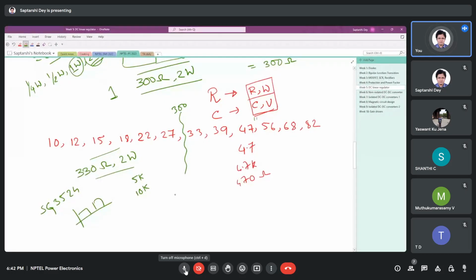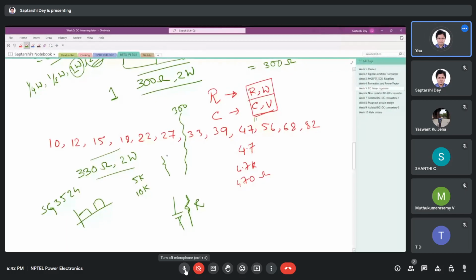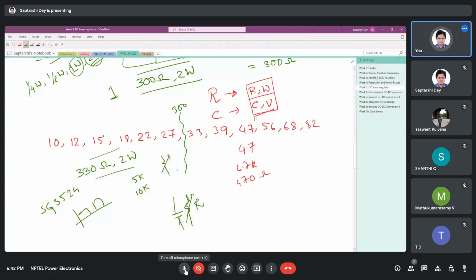There we need a certain RC value so that we can control the frequency and duty ratio. One resistance will control frequency, the other will control duty ratio. So instead of fixed resistances we give pots so that we can vary and precisely control the duty ratio and the frequency. Fixed resistance will be of no help there. They will give a fixed frequency and duty ratio.